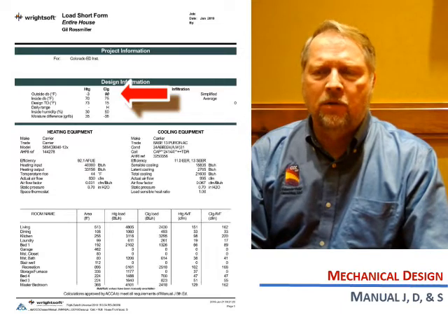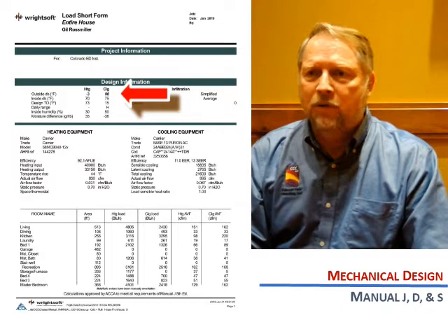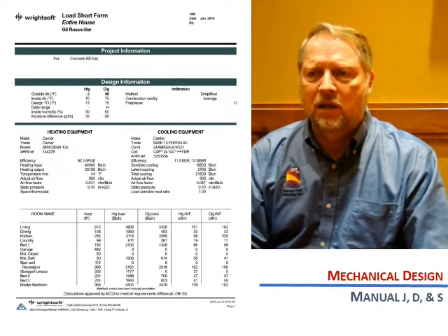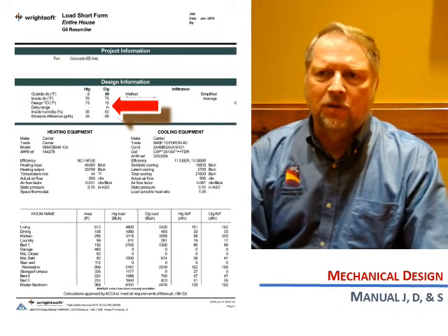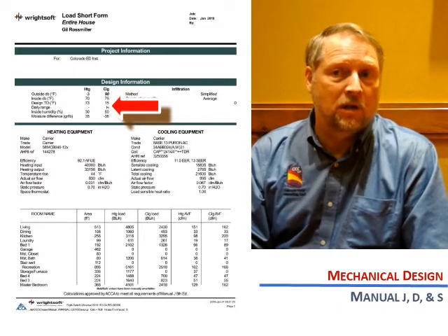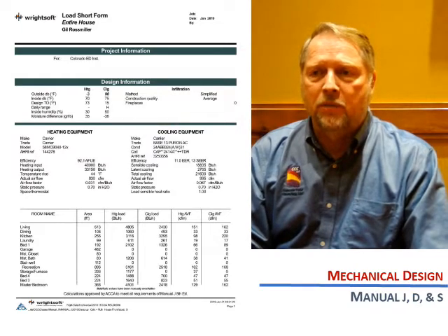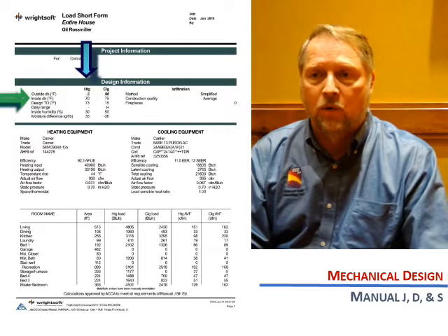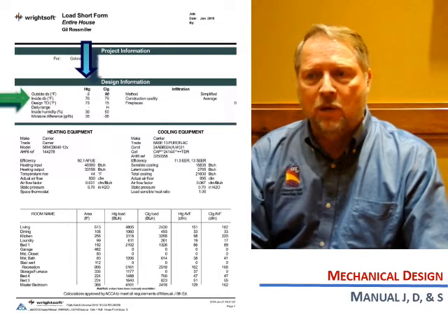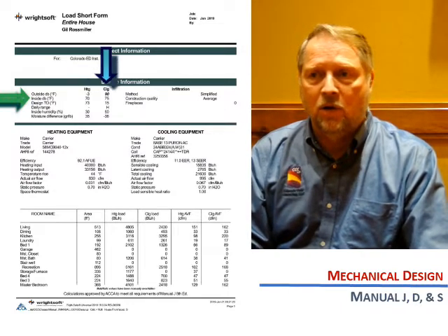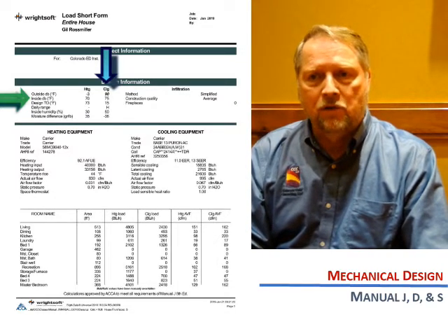Just know that Manual J version 2, the current version, was published in 2006, and the weather data may be slightly outdated. All ACCA approved software will contain updated weather data. Verify the daily temperature range for this project, maybe it's listed as high, low. The last portion, dealing with the indoor parameters, is labeled either as heating and cooling or winter and summer. You're going to verify that if the indoor heating or winter temperature is 70 degrees, that's what we're designing to indoors, and that the indoor cooling dry bulb temperature is 75 degrees.